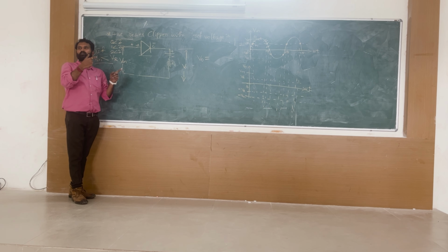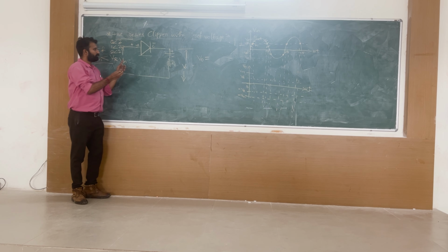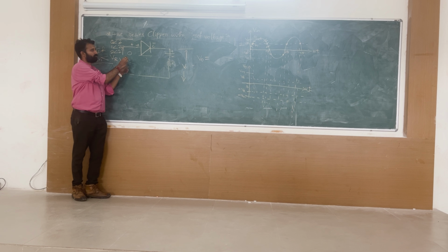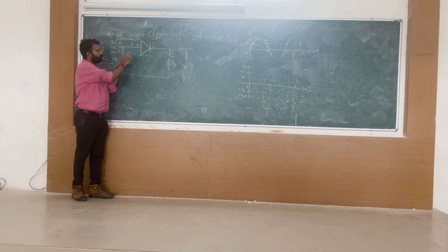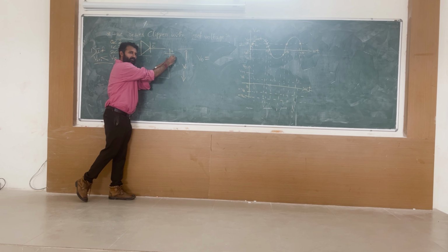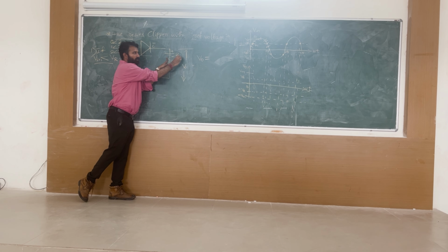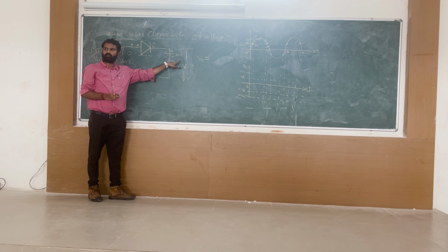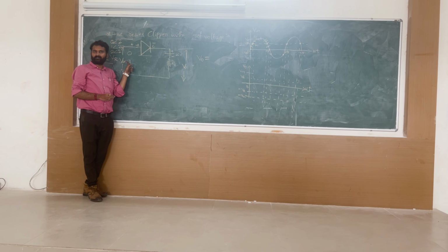Focus here. Everybody focus here. That's a major important concept. Focus here. I am applying 0. 0 is considered as positive. Say yes or no. 0 is positive. Positive to the positive, negative to the negative. 1, positive to the positive, negative to the negative. 2, positive to the positive, negative to the negative. But my reference voltage is how much? 2 volt. My reference voltage is 2 volt. That is greater than your input voltage. Say yes or no. That is greater than the input voltage.